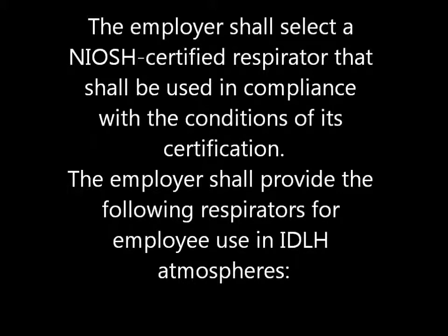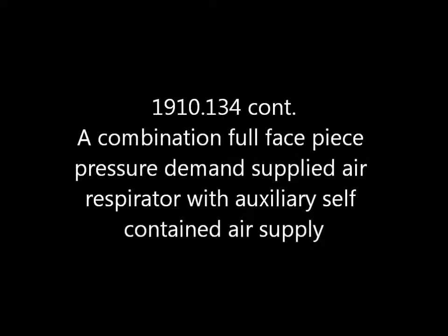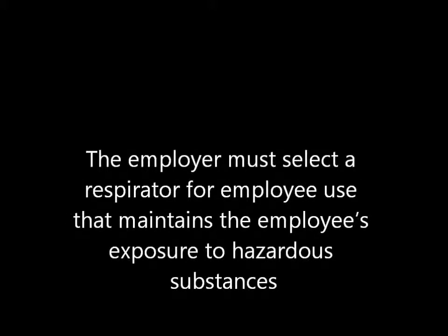The employer shall provide the following respirators for employees' use in IDLH atmospheres: a full face piece pressure demand SCBA certified by NIOSH, or a combination full face piece pressure demand supplied-air respirator with auxiliary self-contained air supply. The employer must select a respirator for employee use that maintains the employee's exposure to the hazardous substance below acceptable limits.